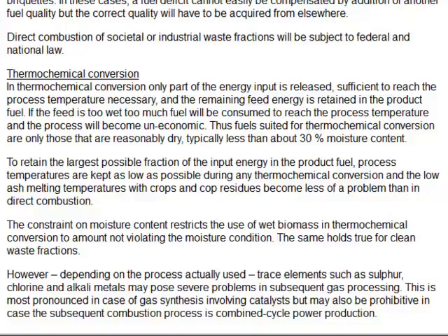Hence, what you want to do is to run the process at the lowest possible temperature to obtain a complete conversion of the feedstock into the product fuel, or as a complete conversion as you can reach, but to keep the process temperature as low as possible. Because to keep the process temperature, what you do is that you oxidize a little bit of the fuel, of the feedstock. So you consume a bit of the feedstock to maintain the process temperature.